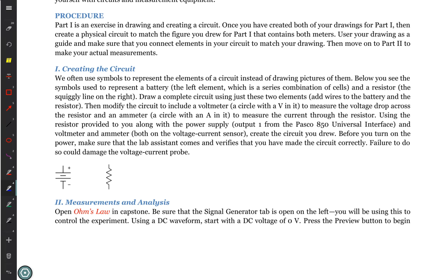And the first thing I'm going to do is connect my circuit as we had for the first one to make a complete circuit. So I'm going to take my resistor and just clip it, make sure it's actually making connection, clip it in there, and I have the resistor now making a complete circuit. Not hard, right? Now I'm going to connect only the voltmeter.